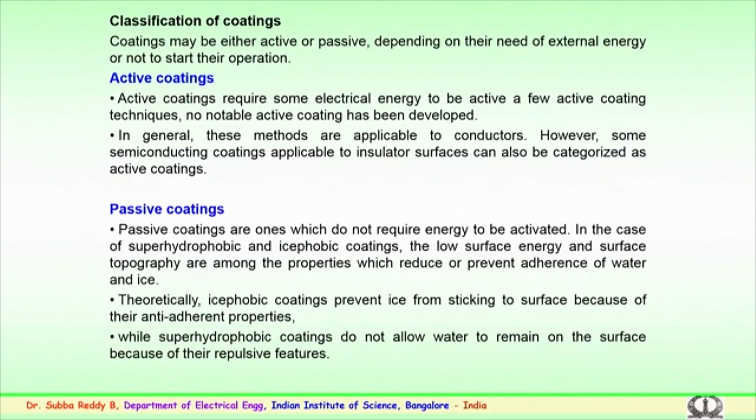The ice should not stick to the surfaces, either a conductor or the insulator, because of their anti-adherent property. While super hydrophobic coatings do not allow water to remain on the surface because of their repulsive features. So, this is like hydrophobic coatings, but much better: more water repellent property is embedded in the super hydrophobic coatings, which do not allow water to remain on the surface.